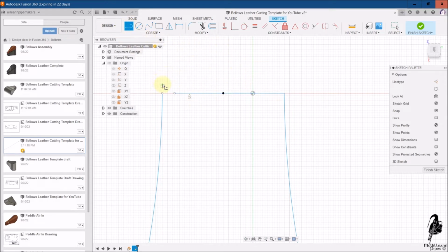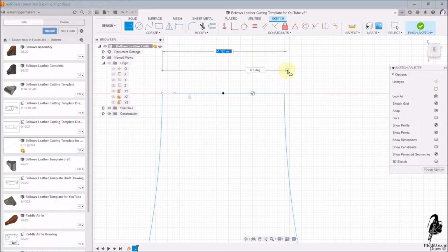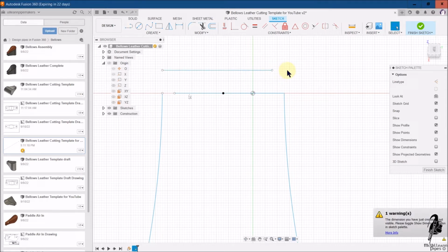But first thing we'll do is we'll take our start position with reference to that point, and if you just put the cursor on the point and draw it vertically upwards from it, you'll see it's getting a dashed line to show that there's going to be positional link between the 2 points. Click, and we'll now make our 45 mil line, and it's directly above that point there, but not connected to it yet.